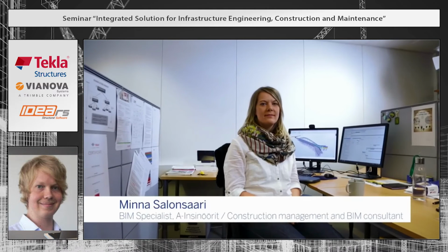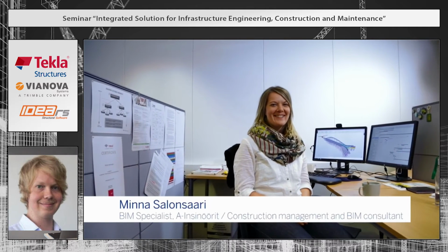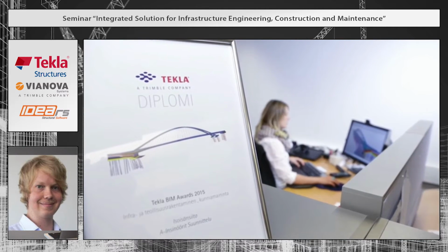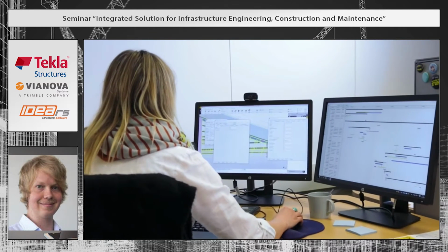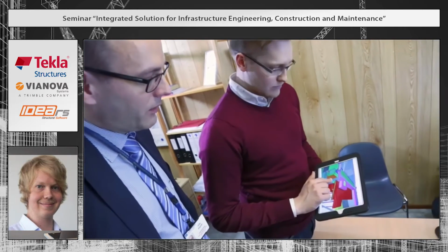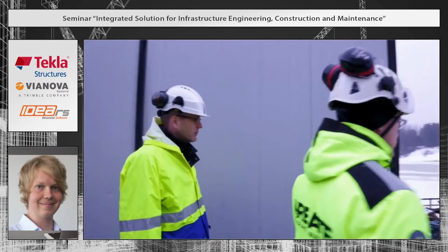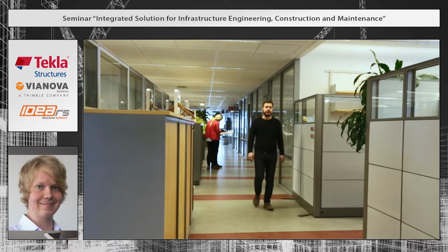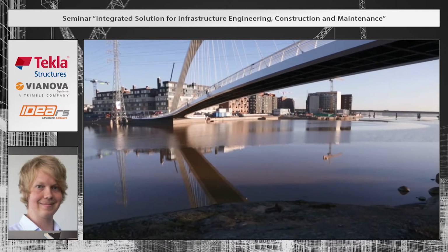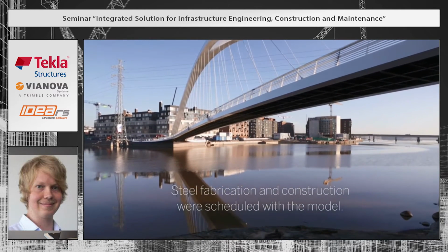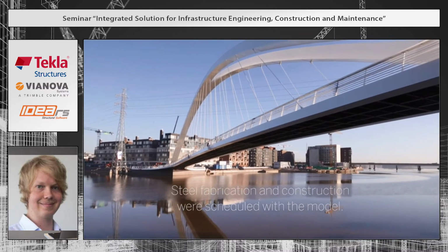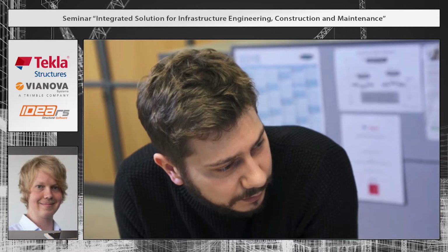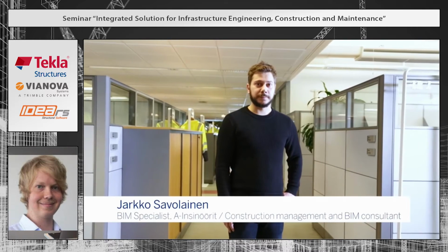When inviting tenders and during the bidding phase of this project, there was really only the model, and that was the starting point. In addition to contracting, the model was also used for logistics, specifically for scheduling, meaning that the contractor added the schedule of when the design process was to be finished into the model. For example, the design schedule of the steel structure, the manufacturing schedule, and the installation schedule were in the model all the time, allowing us, for example, to make sure that fabrication was well ahead of installation.